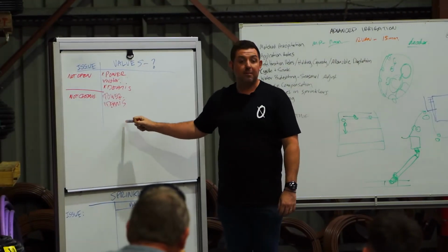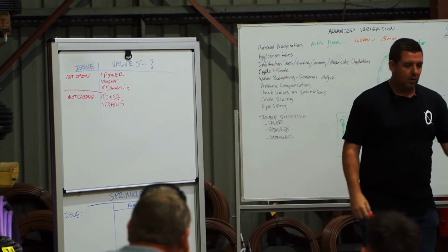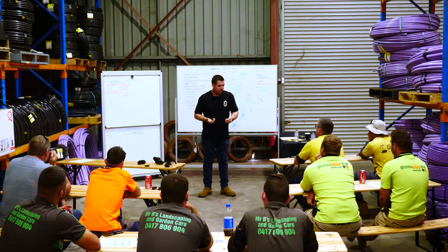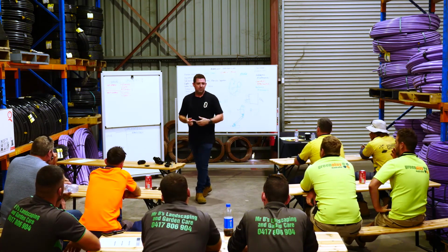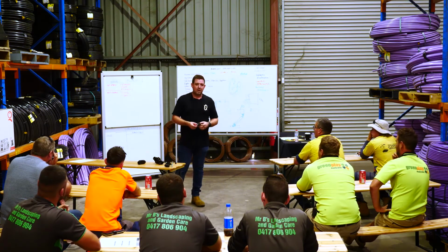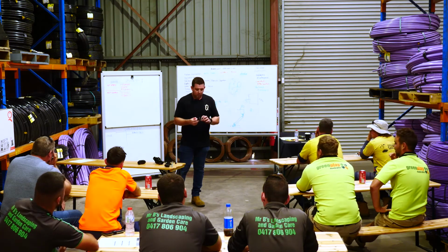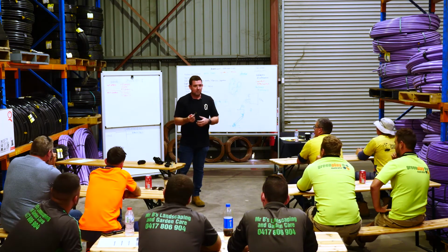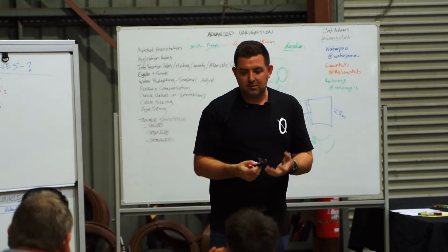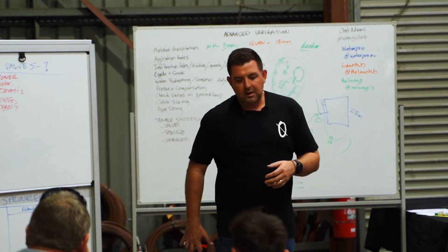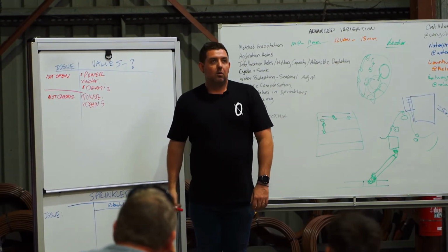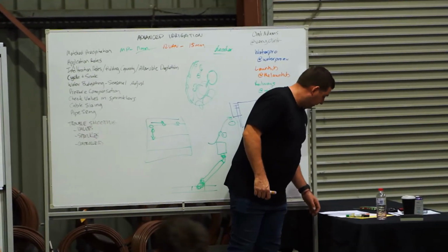Debris, damage. I don't know, I haven't worked on site for a long time. Are you seeing damaged valve diaphragms? No, it's not a thing. You'd be looking at 20 to 25-year-old Rain Bird valves that have just been operating for so long that they've deteriorated. They're always lubricated. They're a plastic or a rubber, so there's nothing much that can go wrong with them. So it's very uncommon that it's not closing because it's torn, but it's something worth knowing. What else is there? And I'm asking genuinely, I can't think of anything else.